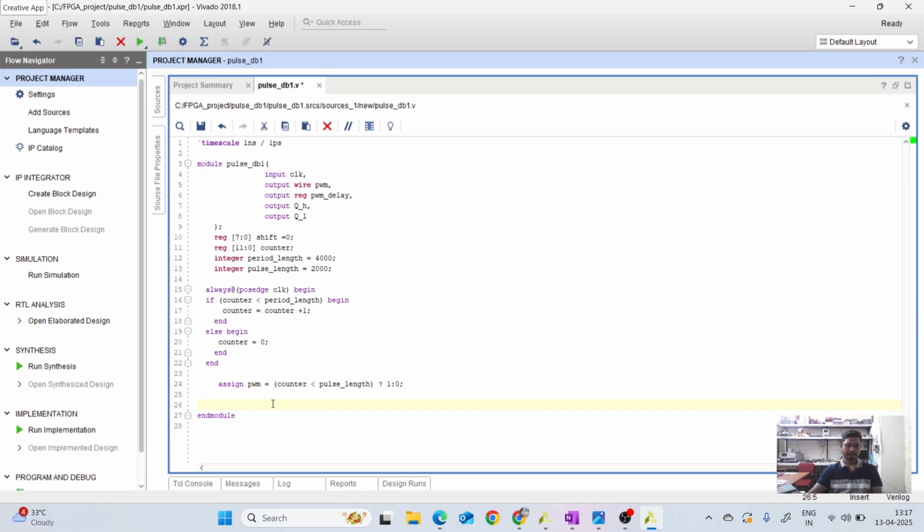So we have to make another always block. Always @(posedge clk), begin. Now shift[0] <= PWM.